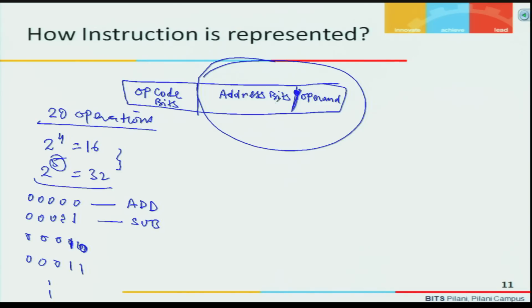So this is what is called the addressing modes, meaning where the operands are, how the operand is represented in the instruction. So definitely some bits I require in the instruction that tell me exactly where the operands are. Registers, then the rest of the bits have to be interpreted such that it is giving me the addresses of the 2 registers from where the data has to be read, and that data I have to use for doing the add operation.